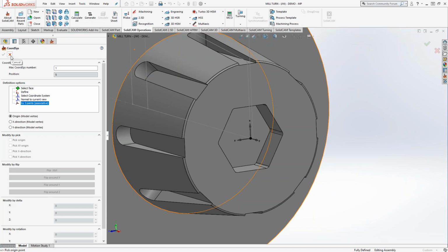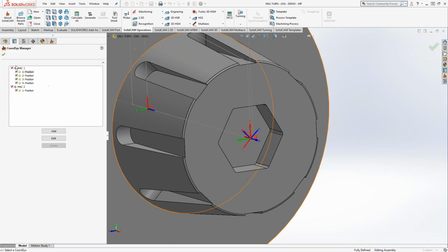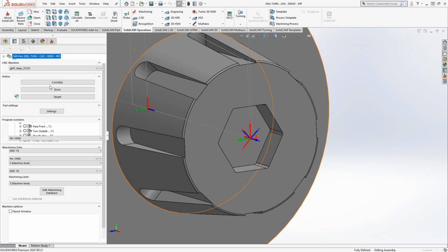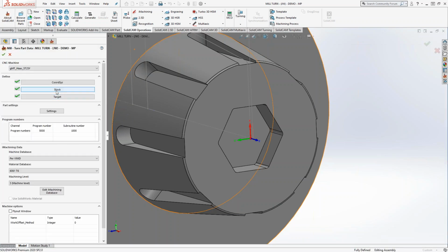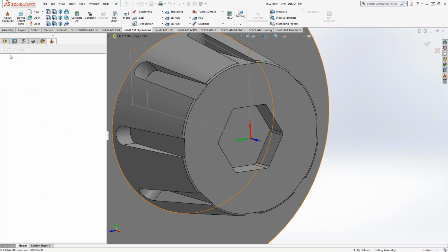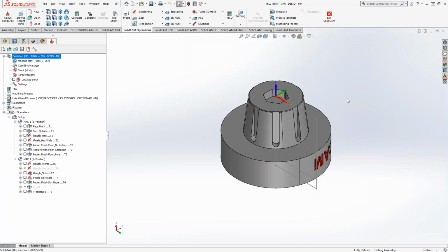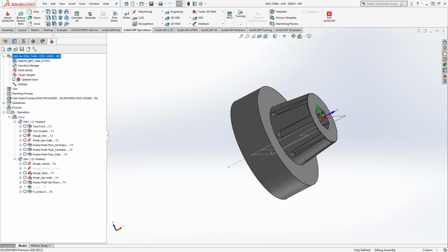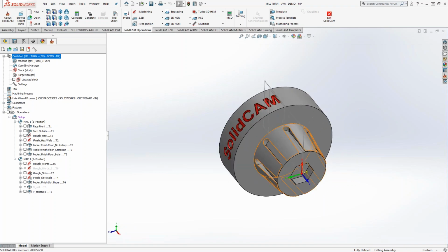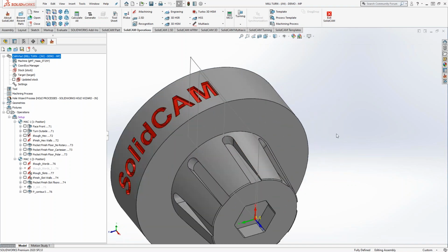That could be really complex if you just have point cloud, because once you've done this, there really isn't anything for you to assign as your target or as your stock. You can put a box stock or a cylinder stock around your part, but ultimately you pretty much are using just point data for simple toolpaths, drilling, pocketing, profiling, if you have that geometry at least. But with points, there's not much you can do unless you turn that into something. But yes, you can absolutely bring in X, Y, and Z point cloud data.